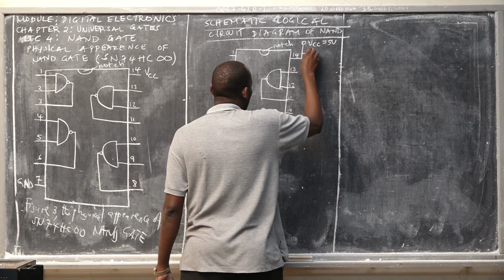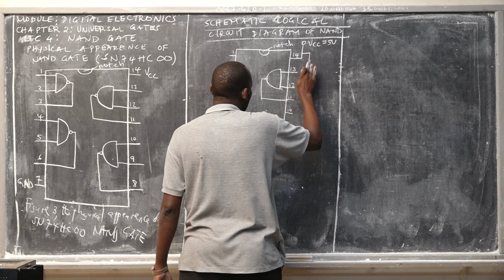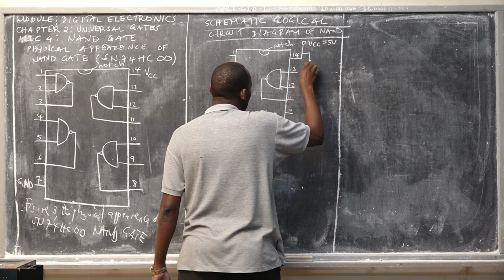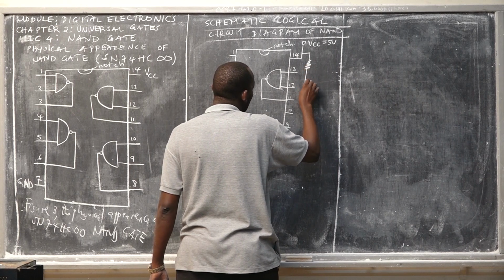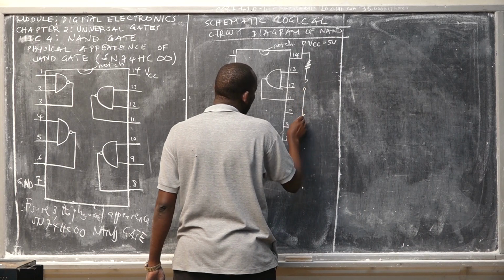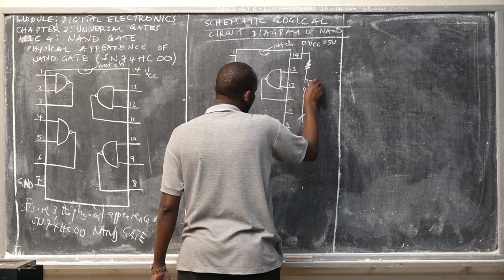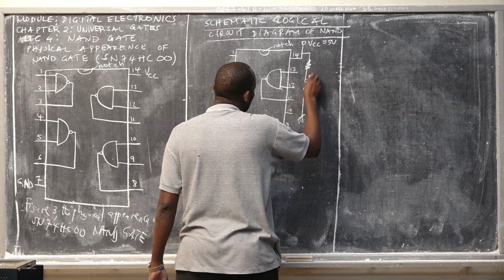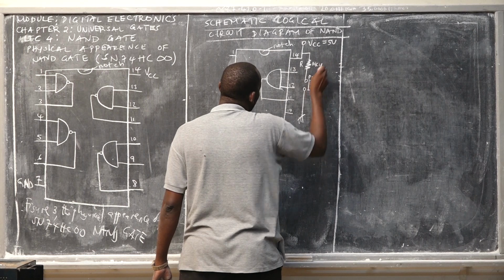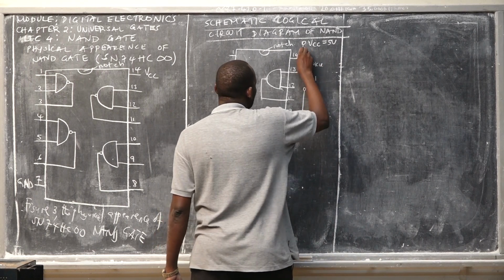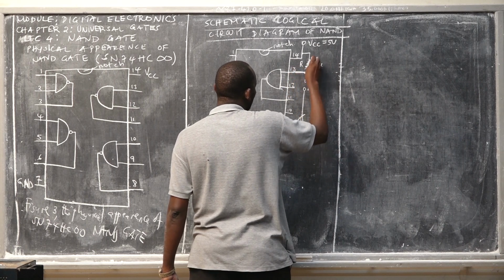So then what do we need? We need to have a pull-up resistor network. So you are going to have a resistor, and you're going to have a push button connected to the ground. This is push button number 1. This is the pull-up resistor, 10 kilo ohm. So we supply the input from here.